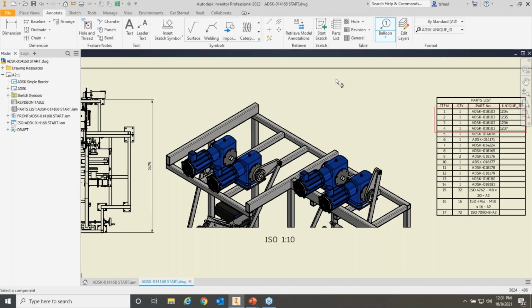And I think the styles are really easy to create inside of Inventor. And essentially you just create those, add those to your global library, and you'll get them available in all your drawing files. So you only really have to do it once, okay? Even if you have thousands of legacy drawings, if you're using a global styles library, these styles can be easily shared to any drawing. So do keep that in mind. It's not that difficult to set up those things so you're using it properly.